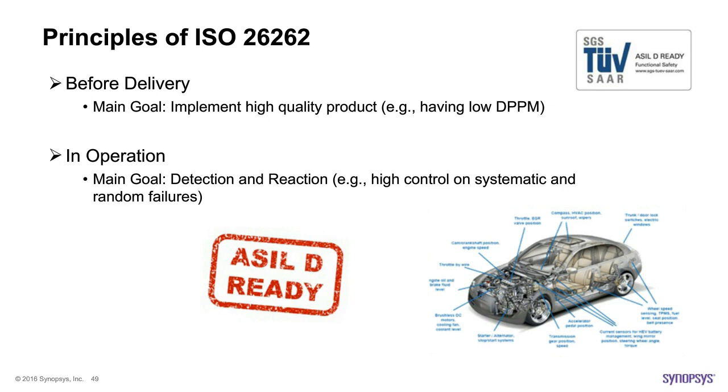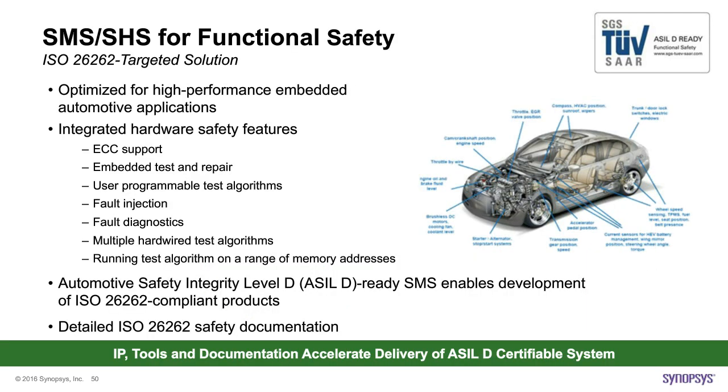And that is how to detect and how to react. The game is that there are certain functionalities that are meant to be run for that safety purpose. That is when the risk happens in the field, when a failure happens, whether it's hardware failure or environmental damage due to soft error, you have your ECC there, you have your self-repair there, and you verify all of that with injecting faults, with diagnosing them, and ensuring that they are all met.